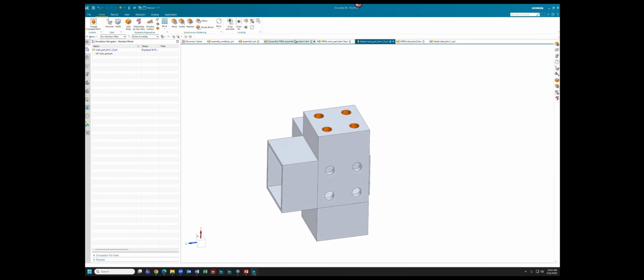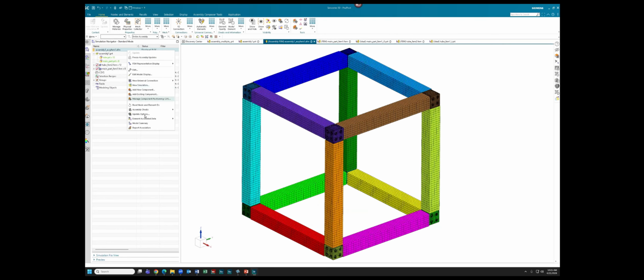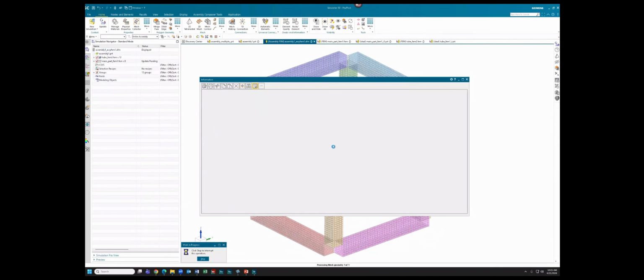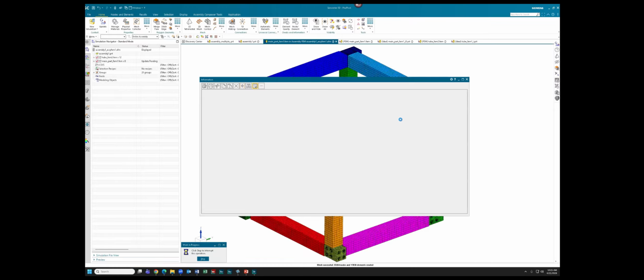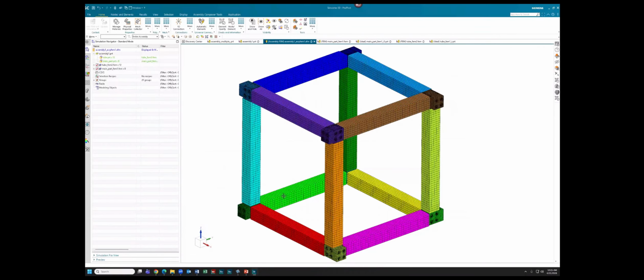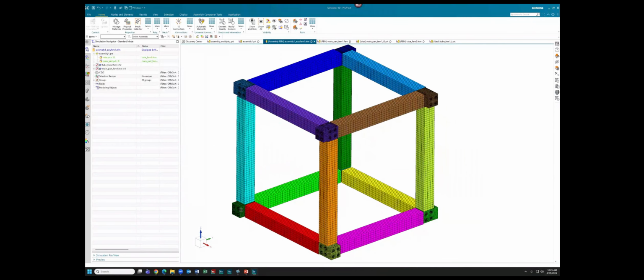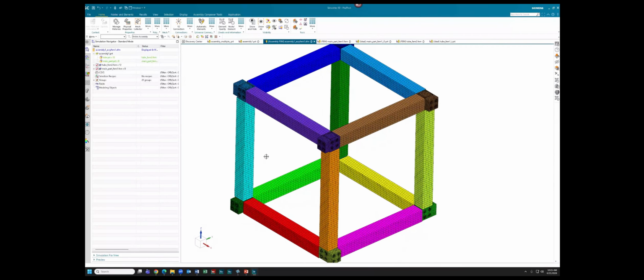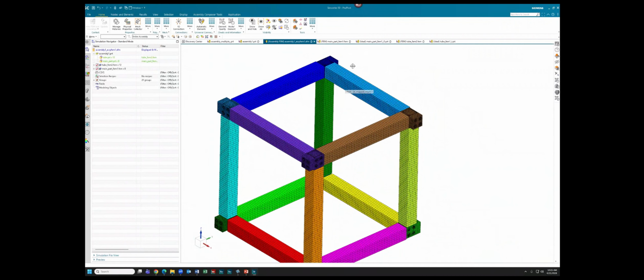So I'm just going to pull one of those faces, and then all I have to do is return to my AFEM and tell it that I have some updates for it to integrate. And then just within a few seconds here, it's going to remesh that component and then remap that updated mesh. And then you can see we have that update propagated throughout our entire assembly FEM. So once again, just a great feature about Simcenter is leveraging that geometry associativity to be able to do these types of updates really easily in tandem with those synchronous modeling tools within your idealized part.